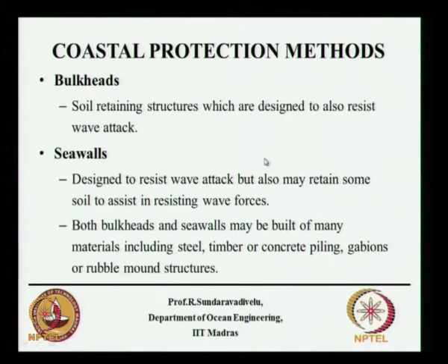There are various methods that are used for coastal protection. One is called the bulkhead, another is a seawall. Both bulkhead and seawalls are constructed parallel to the shoreline. Bulkheads retain the soil, whereas seawalls do not retain the soil. Both are designed to resist the wave attack.